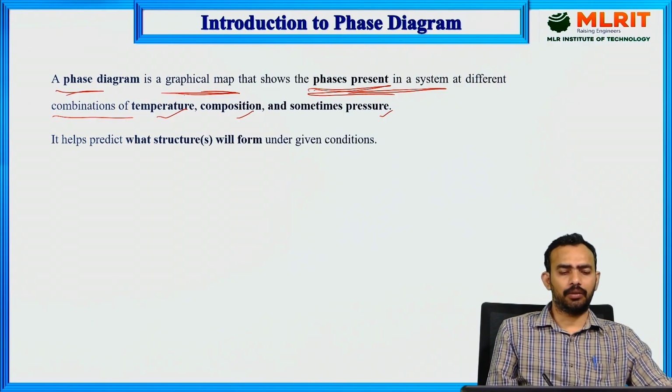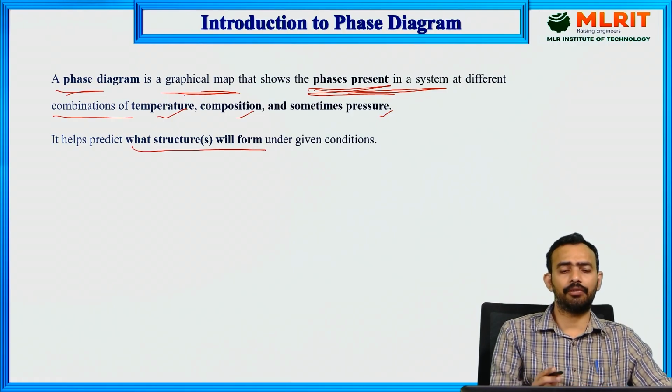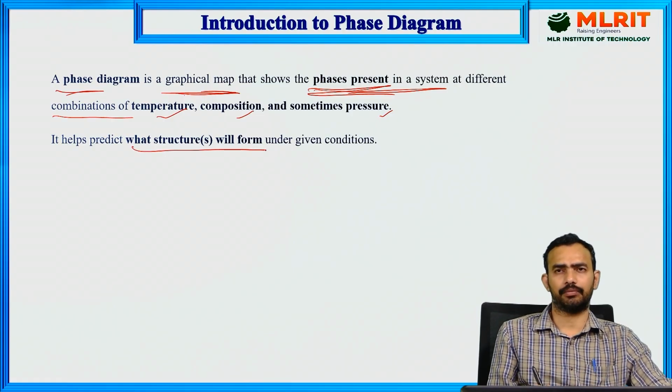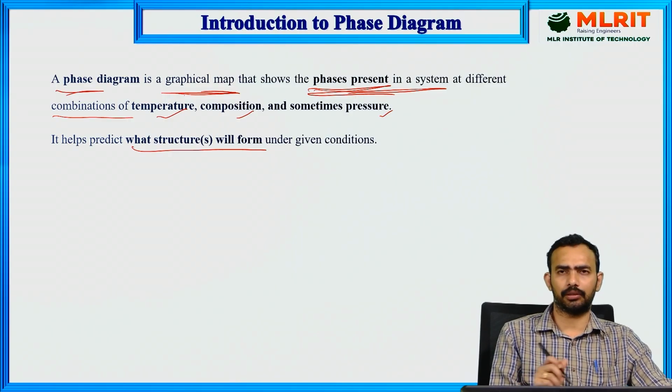Right? What does it do? It helps us predict what structure will form under a given condition, under a particular temperature, composition and pressure. What sort of phase or structure will form in the heat treatment process, we are able to predict it.